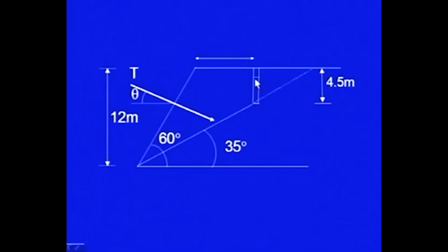So you can also find out what happens if there is a heavy rainfall and this entire crack is filled with water. So V will be maximum. Or you can also do the analysis if the drainage at this particular toe is choked, what is going to happen.